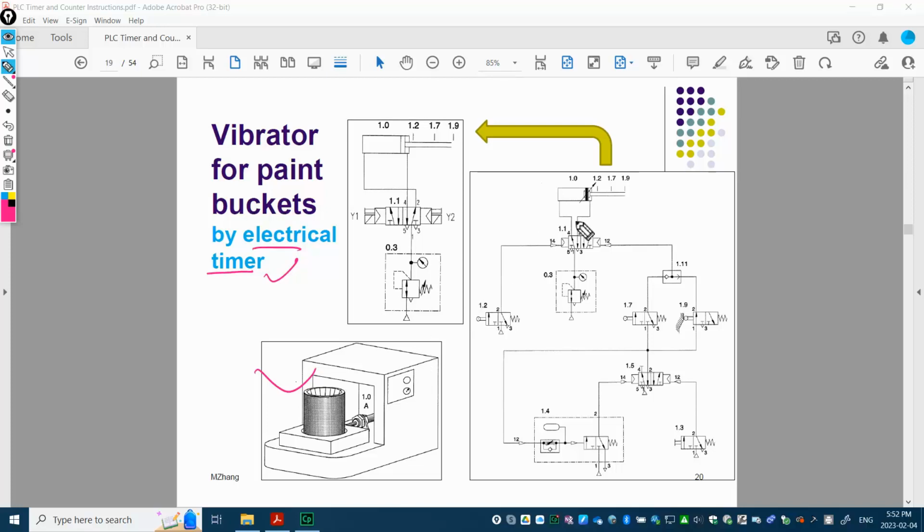By doing that, we have to make some changes to the pneumatic circuit as well. We're going to keep the same cylinder. It's the same as that, right? The most important thing on the pneumatic side is that this was the air pilot control valve, right? So we change that into electrical control by solenoid Y1 and Y2. That's what we call electro pneumatic. Then we keep the same regulator here. That's all we need for the pneumatic circuit.